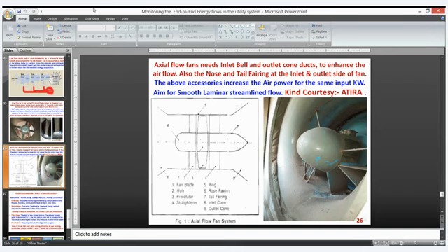Why are we using the velocity recovery rings for all the HVAC cooling towers? The velocity recovery ring tries to restore the turbulence of the flow outside the condenser fan, and that needs to be there not only for the heavy duty 400 ton or 60 ton cooling tower, but even for a 1.5 ton split AC. On the high side outer unit, you can have your velocity recovery ring by a few inches. If it is fixed on the fan, it will definitely tell upon your fan efficiency. It improves your condensing, and the heat transfer efficiency is improved on the outdoor fans also.